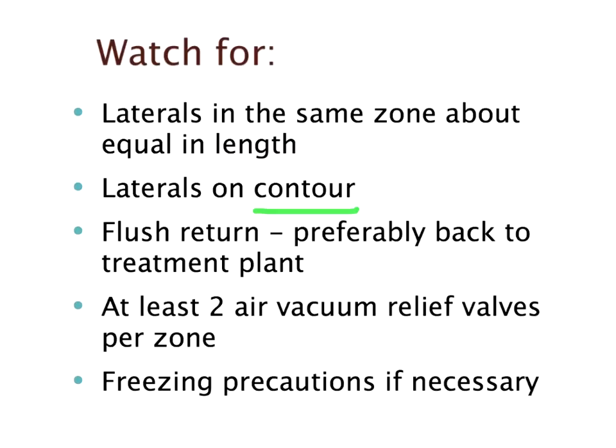At least 2 air vacuum relief valves per zone, and of course freezing precautions if necessary.